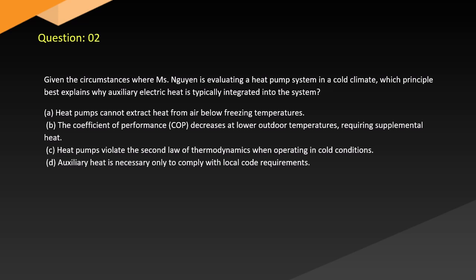A. Heat pumps cannot extract heat from air below freezing temperatures. B. The coefficient of performance (COP) decreases at lower outdoor temperatures, requiring supplemental heat. C. Heat pumps violate the second law of thermodynamics when operating in cold conditions. D. Auxiliary heat is necessary only to comply with local code requirements.